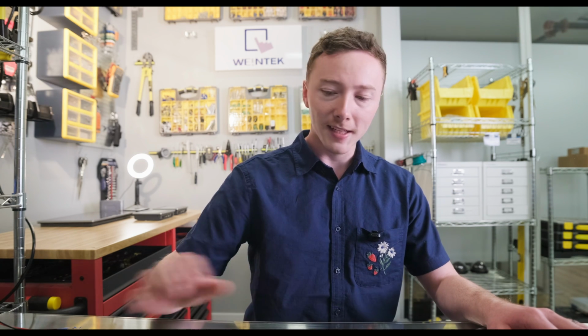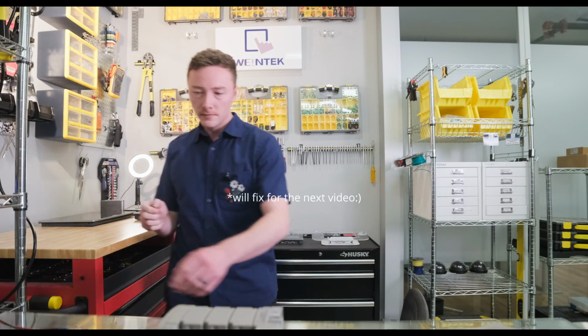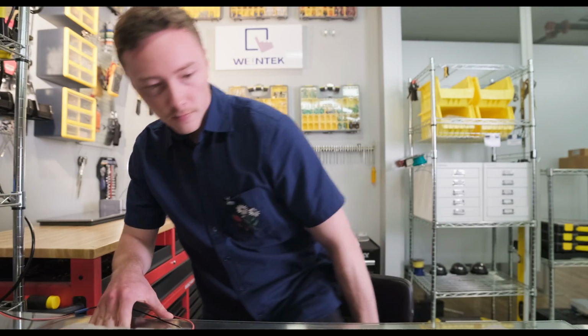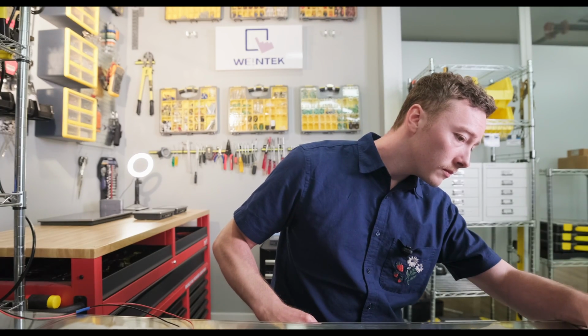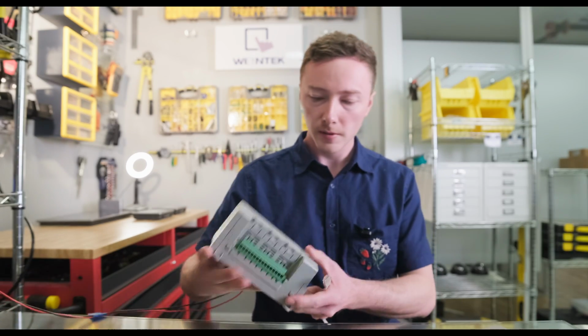So the first step in connecting our Micro 850, it's not listed here, but we actually have to give it power. So let me give it power here. And we'll need an Ethernet cable. And then I'll just pop that into our PC here. And our Micro 850's all booted up.